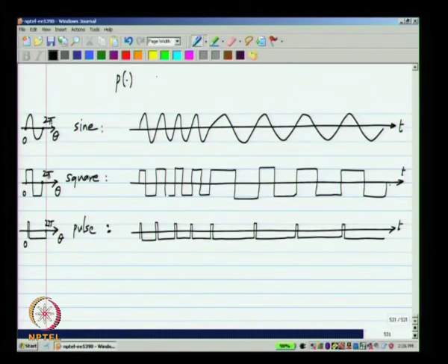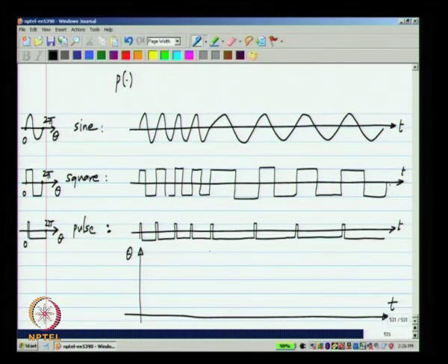The main reason is that we are only interested in whether the signals are periodic or not, and not really what the shape of the signal is. Okay. So, in all these cases if you plot this theta versus time, up to this point it has a higher slope, and after that it has a lower slope. What I meant to draw here is a constant frequency and a lower constant frequency. So, that means that phase is ramping up to this point, and again after that it also ramps up, but with a much lower slope.